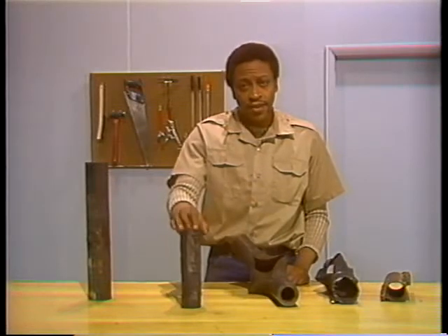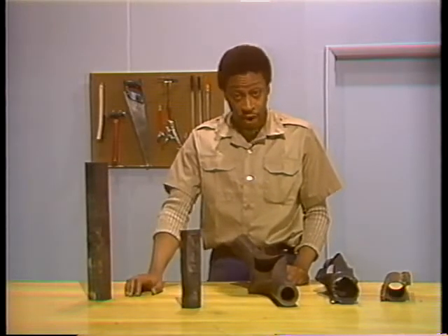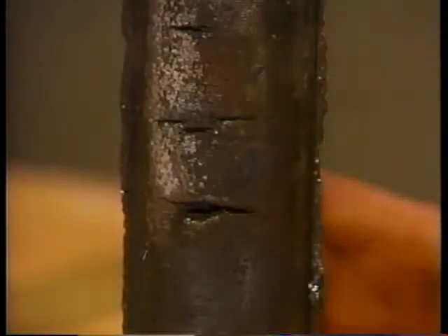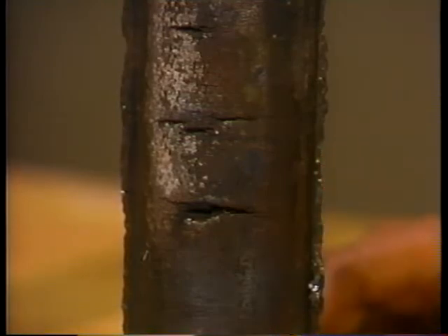Thermal cracks, sometimes called creep cracks, are another type of tube failure. Prolonged mild overheating or repeated short-time overheating creates thermal cracks. The cracked wall will have a normal thickness, but the crack itself will have a dark, crystalline appearance.